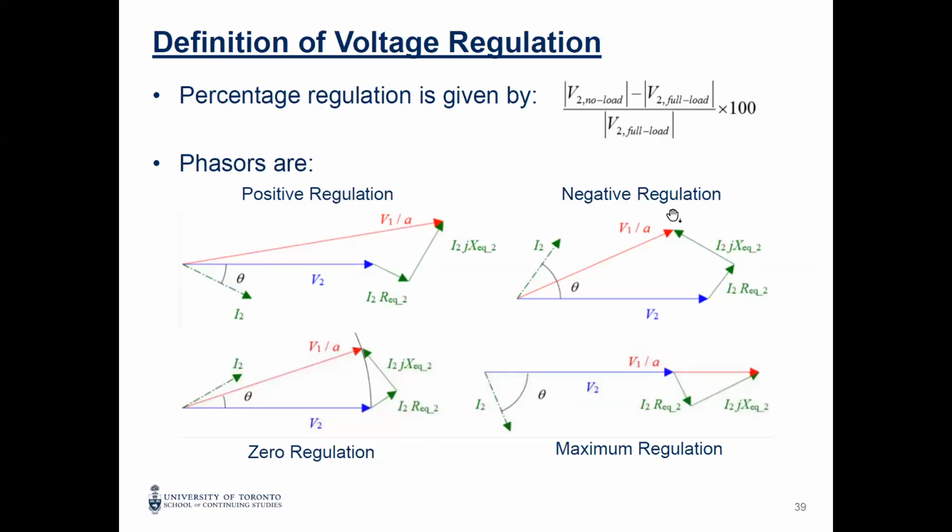This section is very, very small. We are going to go through it quickly, and we are going to solve one of the exam problems to make sure that you understand. It's something called the VR, or voltage regulation. In the exam, after you get the four parameters RC, XM, R equivalent, X equivalent, and you have your circuit of the transformer, we call it the approximate equivalent circuit.